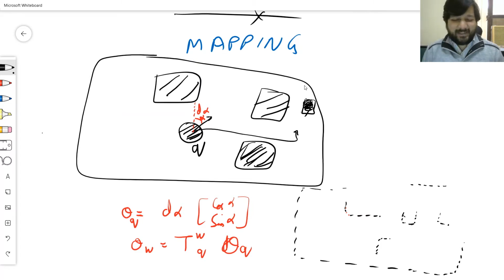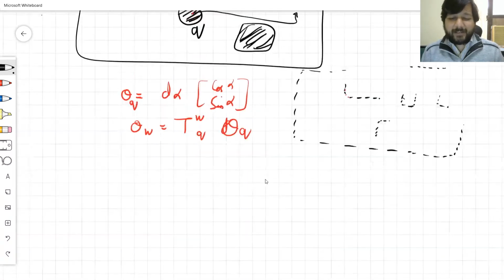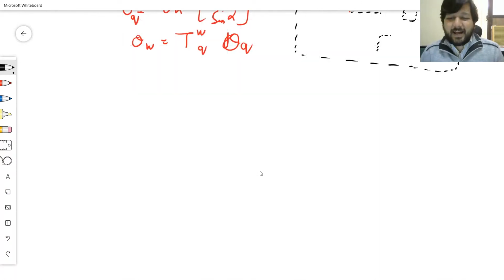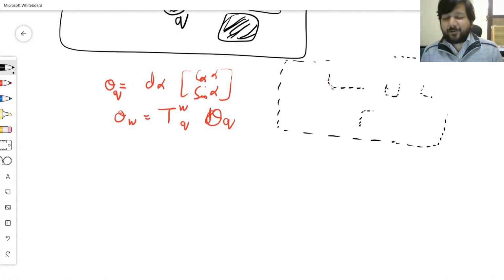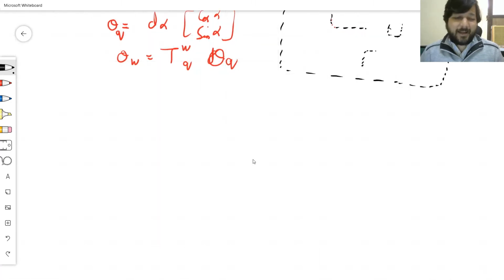What you do is take a majority vote or a probabilistic fusion. When the robot is near the obstacle, it will be able to look at it more clearly. That's when we are using the entire map. If you just need the corners like previously to save memory, you can only project the corners onto this map. And similarly for the case of the camera.